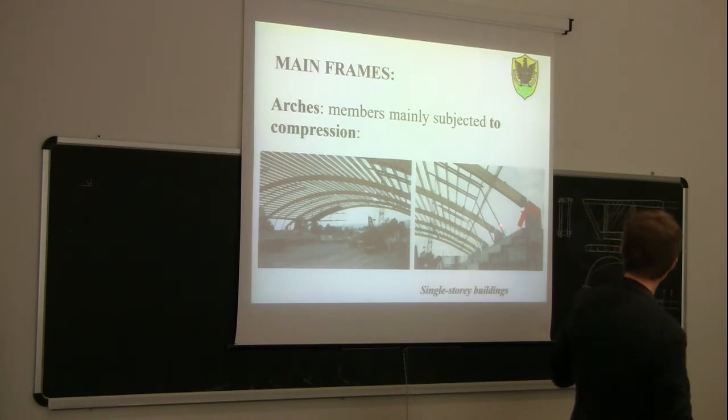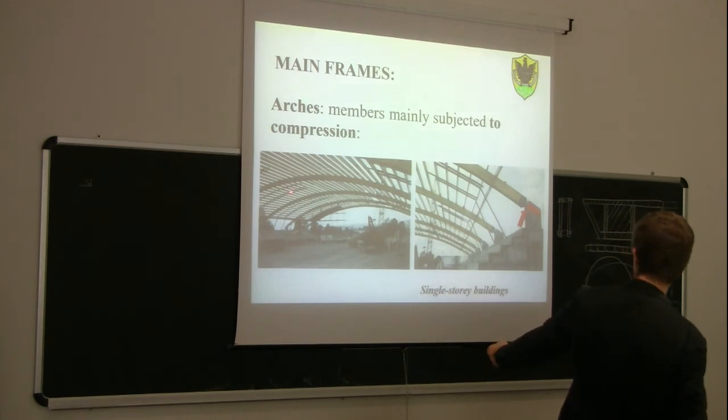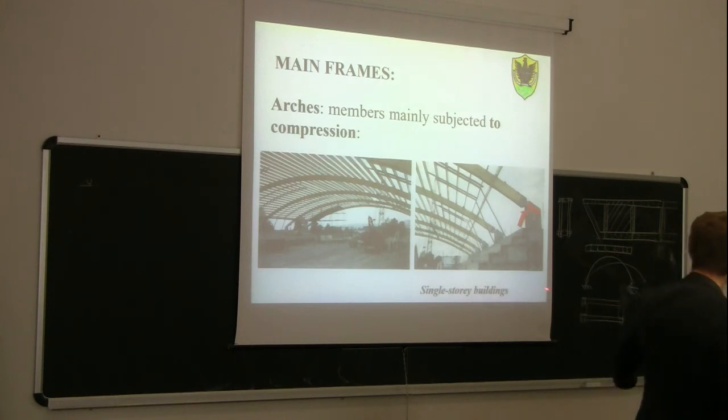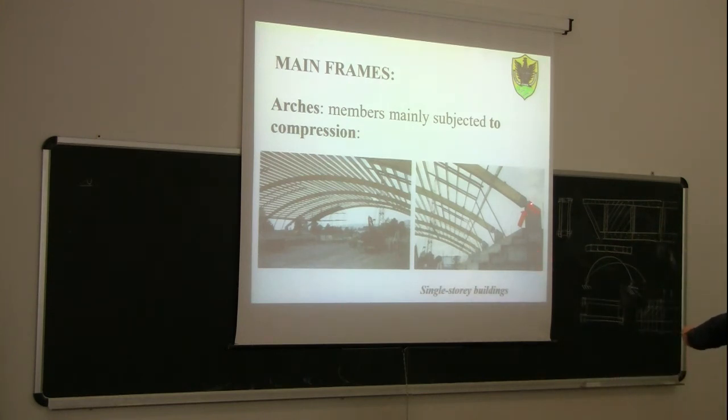This is why you can see here in this arch, this is a very big arch, it's a three-beam arch, you may see there is also a beam in the middle. You can see that at the end here there is a pin. This one is a real pin made of steel. And here you can see that there is quite a squat reinforced concrete cantilever. So this is a reinforced concrete cantilever, a structure made in this way, by reinforced concrete. So, why, for example, here do they use reinforced concrete rather than timber? Because if they had used timber here, the deflection would have been much higher.